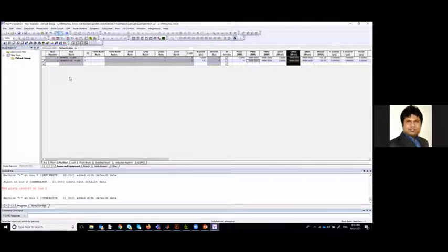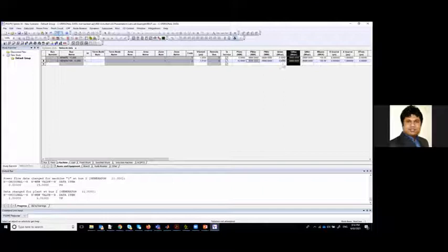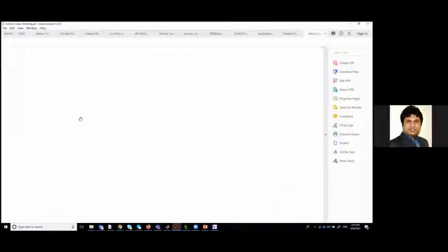Once we put the bus information and machine information, the plant will be automatically populated. If you look, we didn't do anything in the plant, and all this information has been automatically populated. For the machine, we don't know Q; Q is 0. For the infinite bus, we don't know P and Q. But after running the load flow, all this information will change. I'll show you. We still haven't finished the network modeling; we just put this information.